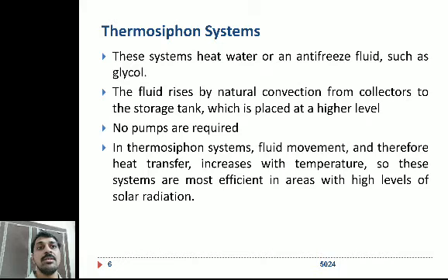Otherwise, what will happen? The fluid inside the tubes of the water heater will get frozen. So some antifreeze will be added in cold countries in order to avoid that freezing and breaking of the systems, pipes. So in the thermosiphon system, the important point to be noted is the fluid rises by natural convection, which is a form of heat transfer from collectors.